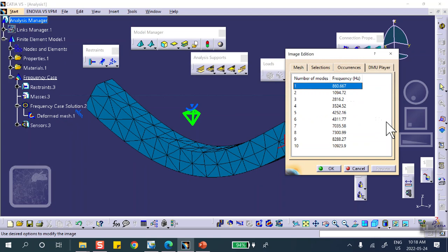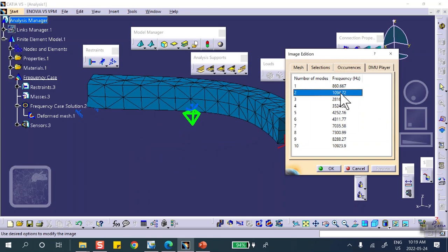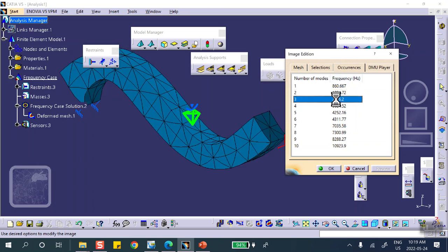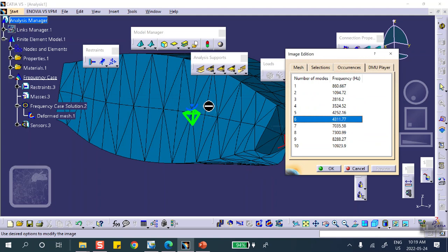860 hertz. Okay, so this thing that I did, whether it's right or not, is going to vibrate at that frequency, at 860 hertz. What about the next one? The next one is coming towards you at a higher frequency. You can see that. What about the next one? This is the second mode of vibration in plane, like that. Second mode of vibration, sine wave. Okay, at that frequency, if you can manage it, somebody held it here and you brought it to that shape and let it go, it vibrates at that frequency. And then you get torsional, and this is a torsional here, look.